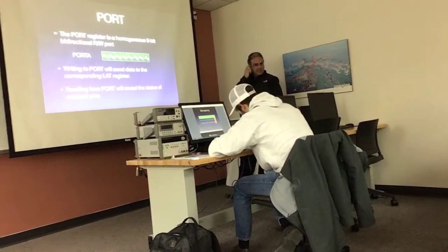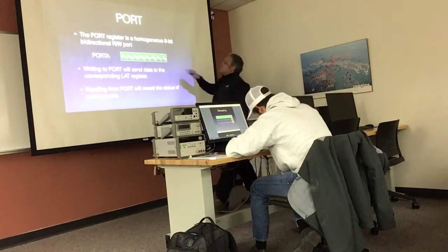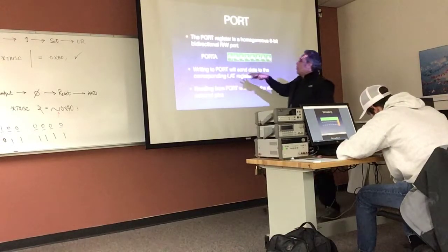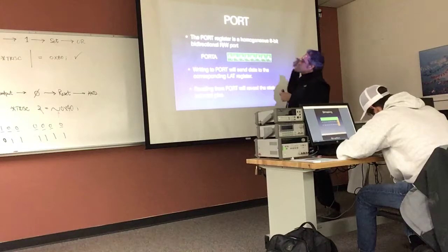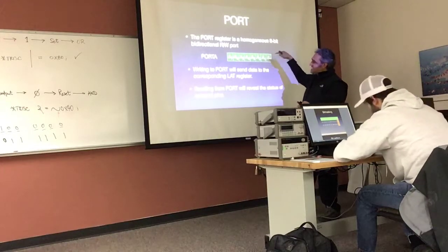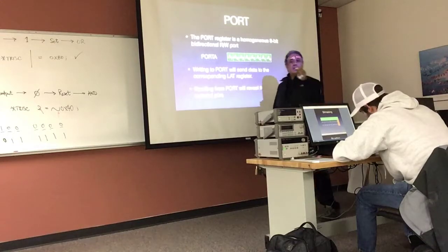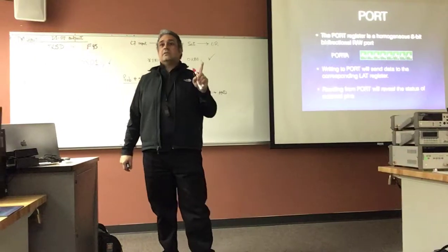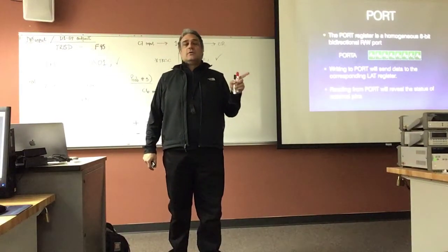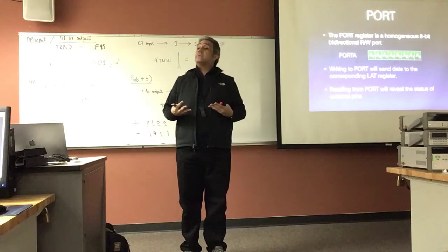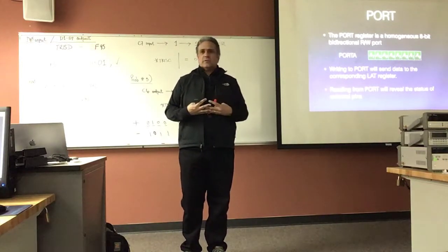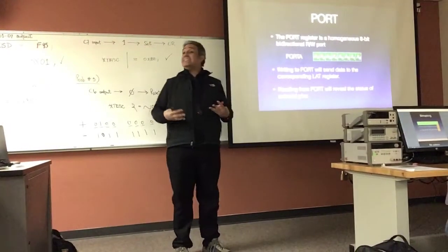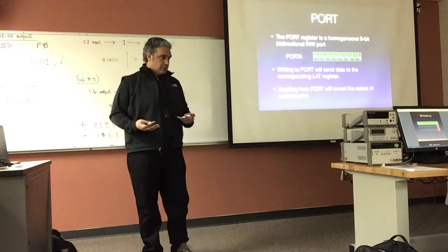But here's the important part, and here's the part that you have to think about carefully. Because this is a read-write port, I can read from it and I can write to it. When you write to the port, if you are physically attempting to write to the port, it will send the data to the corresponding latch. Now, this is important for you to remember. Not every microcontroller can do this. This is an architectural feature of this micro. So one of the first things that you do when you encounter a micro is to see if this feature is available, either by looking at the data sheet or by simply attempting a write to the port and seeing if the latch responded. You see what I mean?